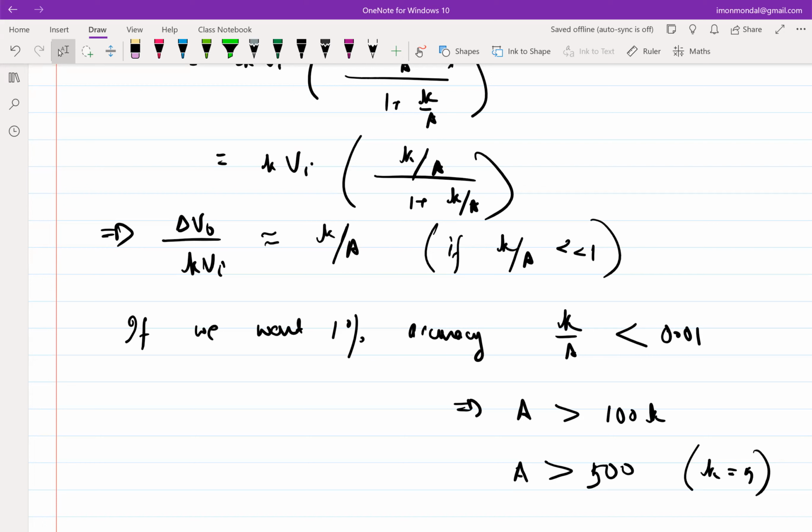If you want to make a precise gain of A, or let's say if you want to make a precise gain of 5 using a common source amplifier, one might say that I will set the GM to some value and RL to be 5 by GM, right? In a common source amplifier, my gain is GM times RL. Whatever GM I get, I choose a value of RL which is 5 over GM. Then I should be able to get a gain of 5.